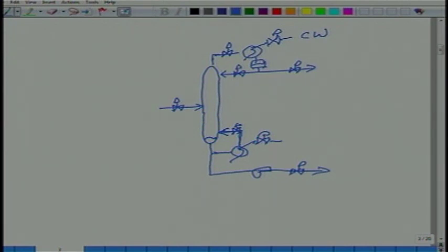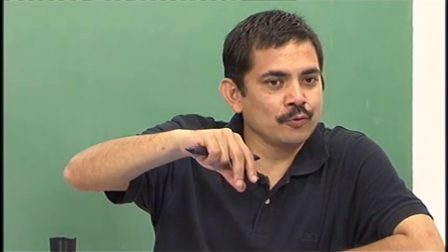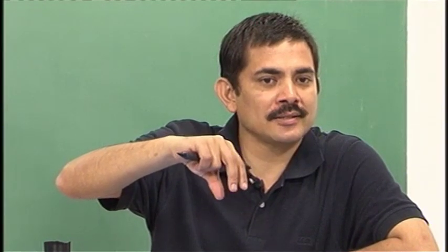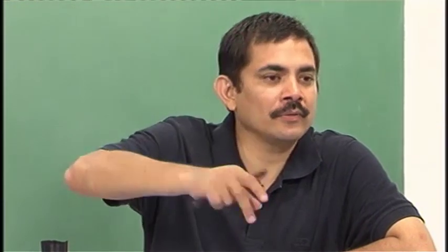In any line, if you want to control the flow, whatever you are moving, that will have to have a large resistance. It has to be the controlling resistance, right? If it is the controlling resistance, pressure drop across that piece of valve has to be large. Do you see what I am saying? Otherwise you can move the valve, flow will not get affected because it is not the controlling resistance. Does that make sense or no?